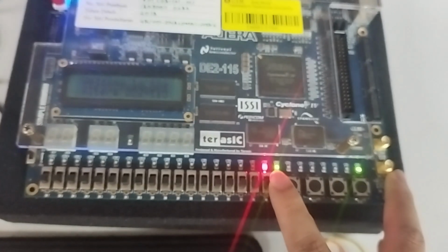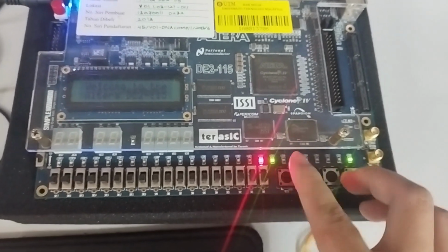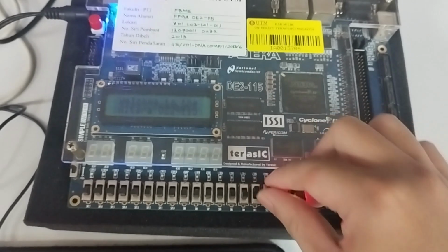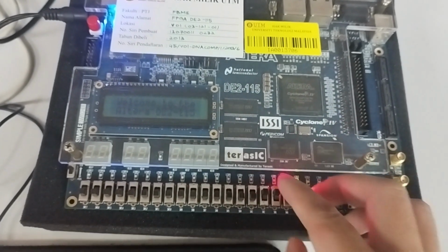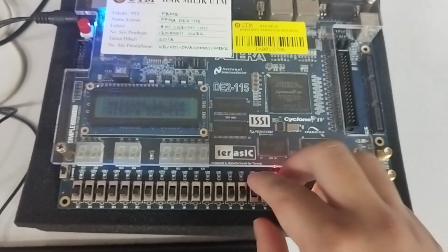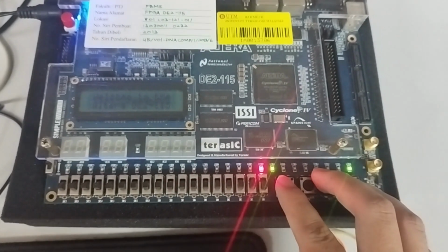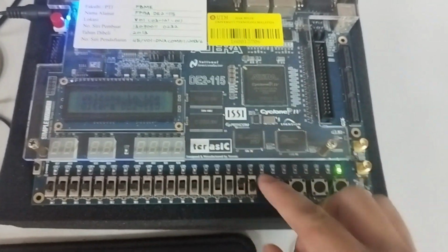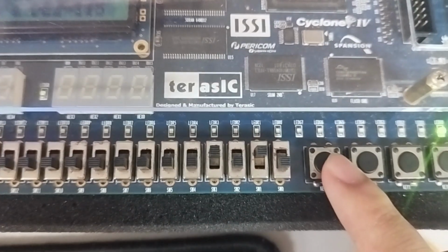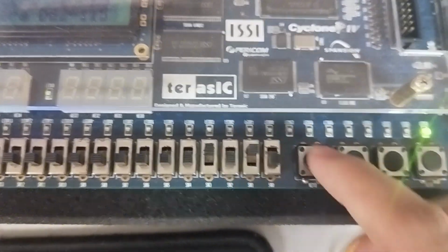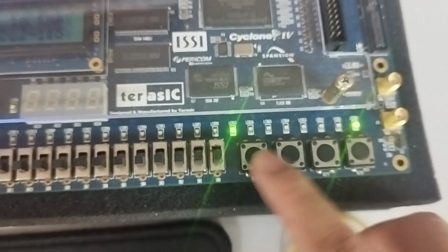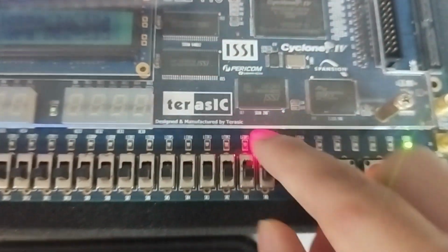If you can see here, hack state shows 2 LED lights indicating that both activate and alert are on. During this hack state, we need to key in the password. As you can see, no matter what password I key in, the hack state is still on as long as I don't input the correct password, which is 101. After inputting the 101, the hack state will transition back into idle state. So that's how the car alarm system works.